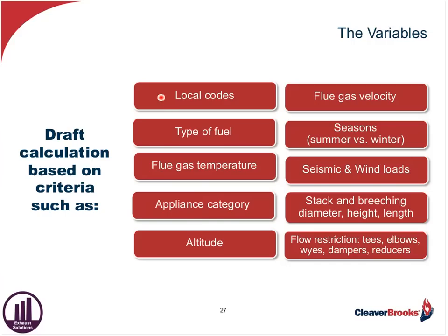What about the local codes? I mentioned the insulating material. A lot of times local codes will dictate under what circumstances certain materials have to be used. For instance, I'm concerned about maybe a combustible wall. I might be running a stack or a breeching through a combustible wall, have to take it through a chase possibly. So the local codes become very, very important for the engineer to make some of the initial assumptions or initial criteria through which he then is going to lay out the entire design.